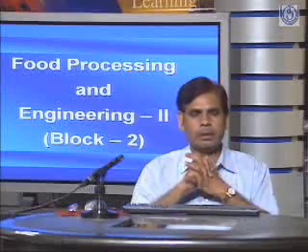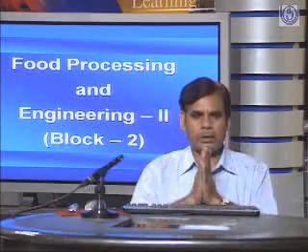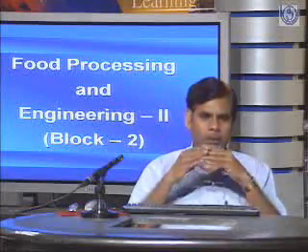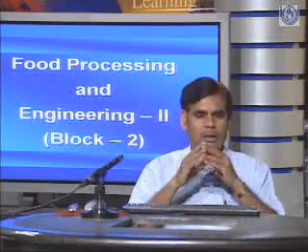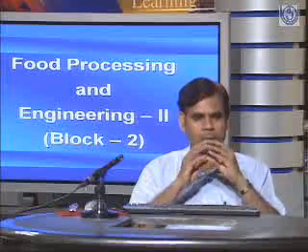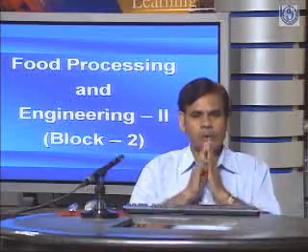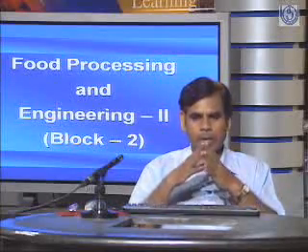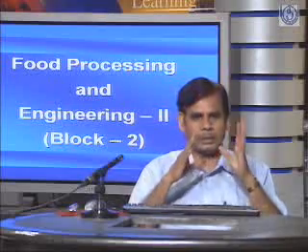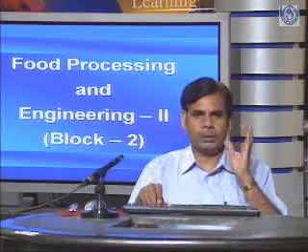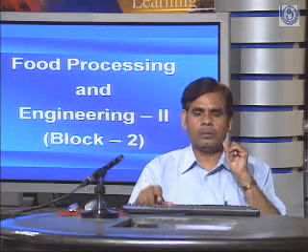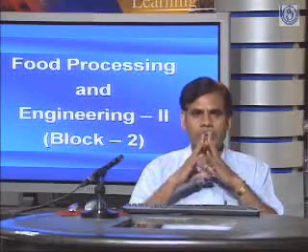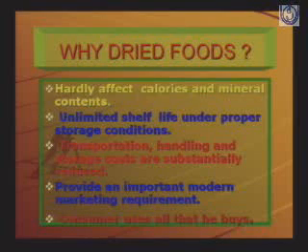The next is normalization. Normalization is nothing but equilibrium with the relative humidity, RH. When the drying process continues, the product dries to a certain level of moisture. After that, it will not dry further, whether you dry for a longer or shorter duration. So if you wish to dry the product to reduce the moisture more, then you have to change the drying conditions. For example, if you dry at a low temperature, then you have to change the relative humidity or drying condition.